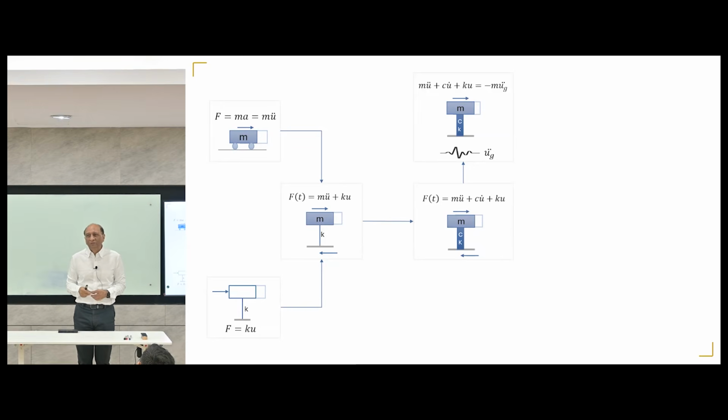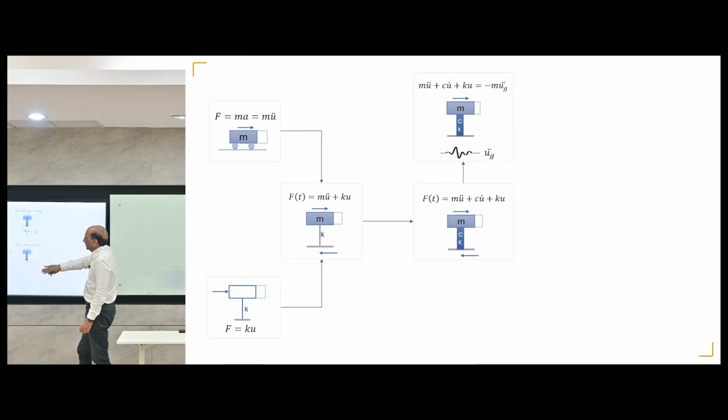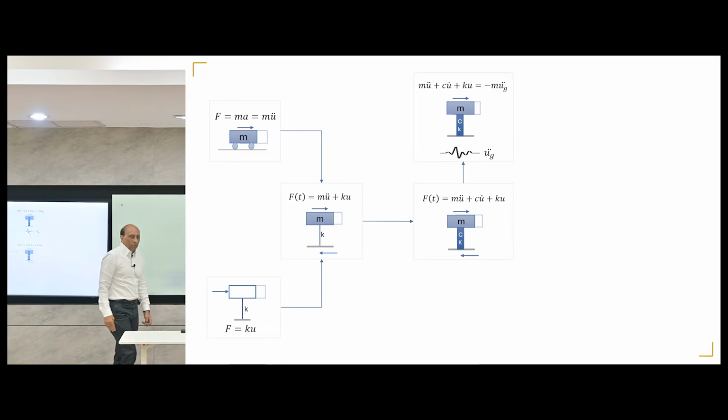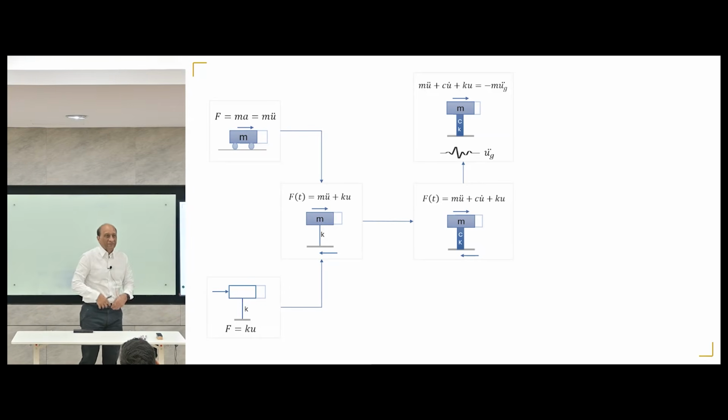So this becomes the ground motion equation. So we have the physics equilibrium, you have the static equilibrium, you have a dynamic equilibrium for an applied force, and this is a dynamic equilibrium when the ground is moving, but there is no force applied as such. But the force will be now generated inside the structure. That force will be generated on this right side, inside a stiffness force, damping force, and mass forces will be generated.